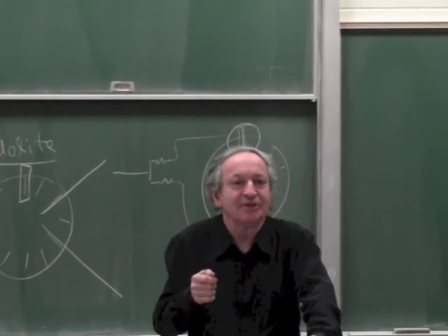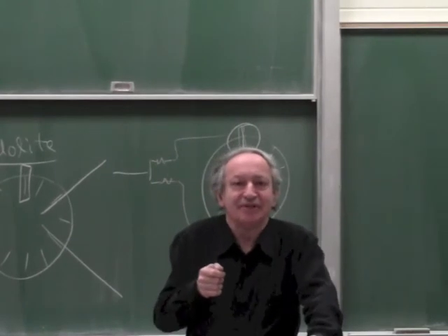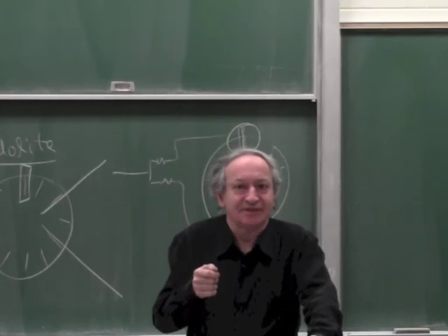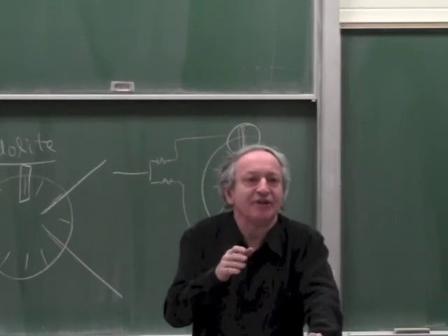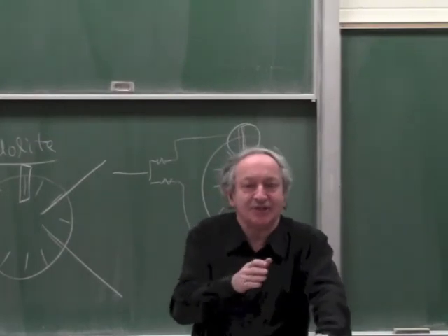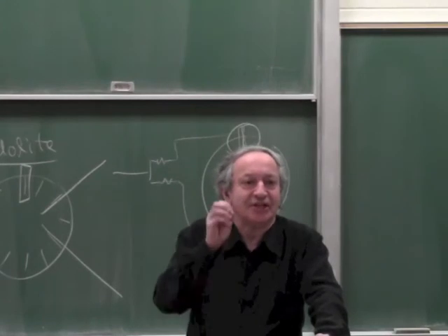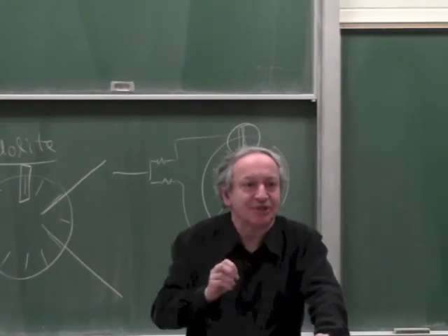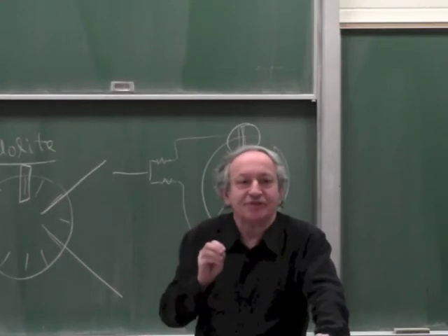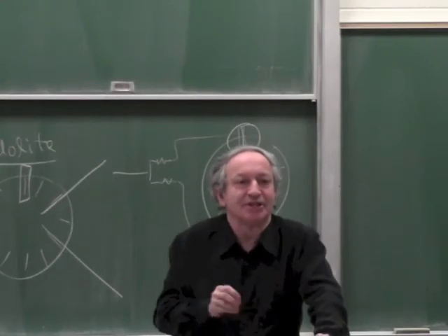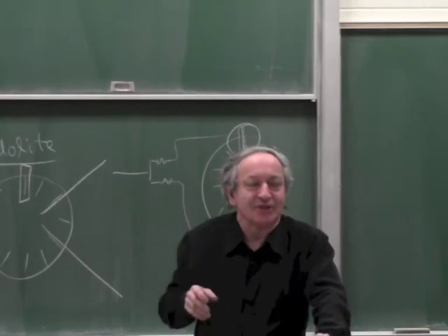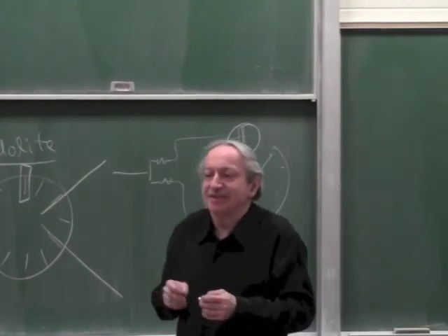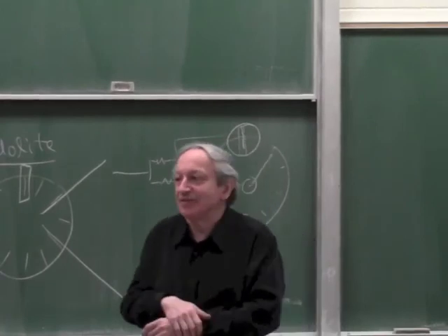Is there anybody here who doesn't know what the sampling rate of an A to D is? Okay. So we are going to cover it next month. I wouldn't get into it now. But when you have an A to D, it doesn't really continuously digitize a signal. It captures a snapshot in time, digitizes. It captures and digitizes. So if this capture rate, which is called the sampling rate, is too slow, it's not aware of changes between the samples. So a camera is a sampling system with a very low sample rate.